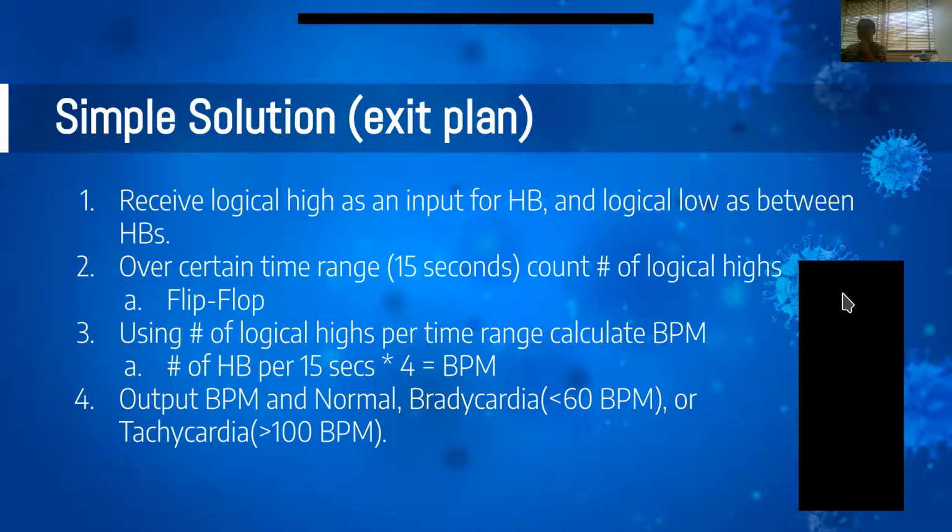I will talk about other things I expect I'll be able to get, but my exit plan will be this simple solution. A logical high, 1 or 0. 1 will mean a heartbeat is happening, and 0 will mean in between heartbeats. And so I plan on using a flip flop. I think I'm going to use a D type flip flop for now,